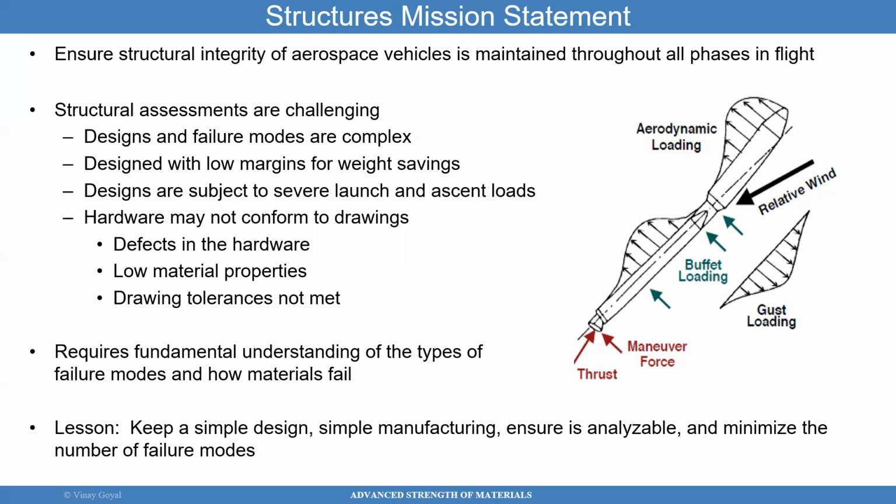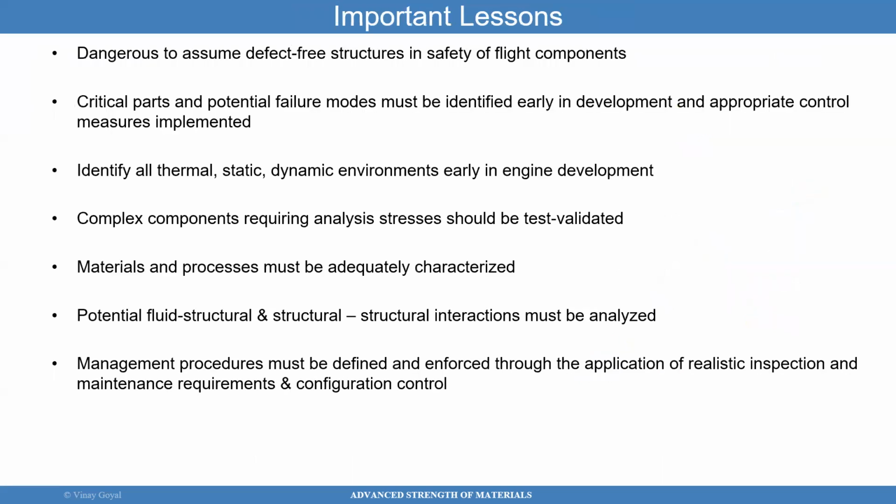And if it's off, somebody's going to ask you, is that okay? That's where analysis comes into play. Testing may be even necessary. If the analysis confidence you have is low, you better test that. If you design the fuselage to be thick about 0.12 inch, but then you manufacture it and come out to be 0.09998, that's a problem. I need to analyze that. But you want to use analysis techniques that are validated.